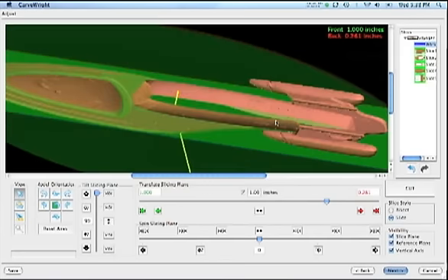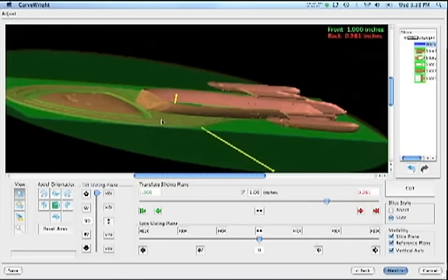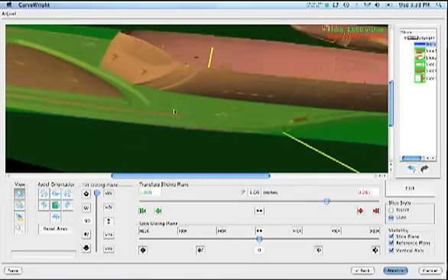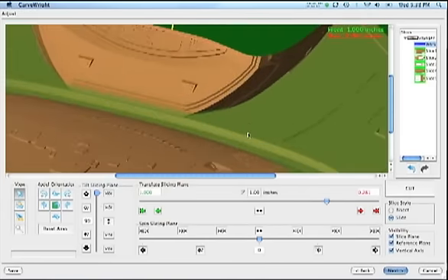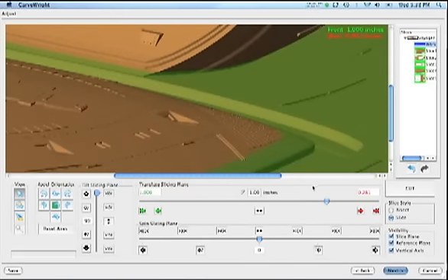Well, first of all, let's see if we can lower this slice down to where we can slice it off right at the base of this. We'll need to select bisect so that we have enough room to move down. So we'll move our slice all the way to that base edge, and let's hit cut.